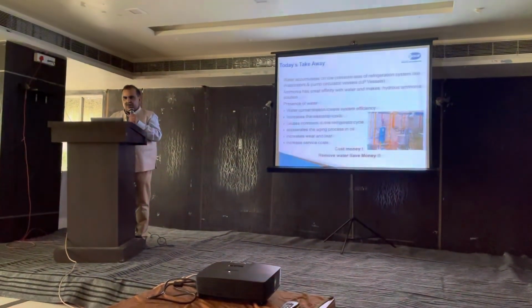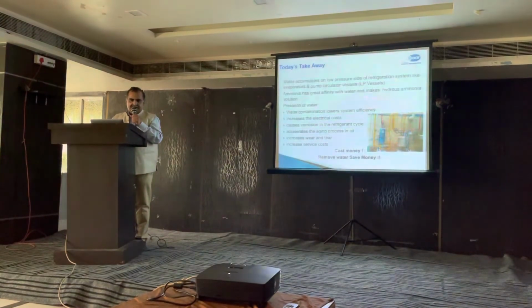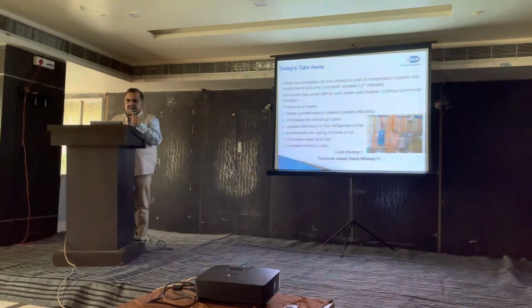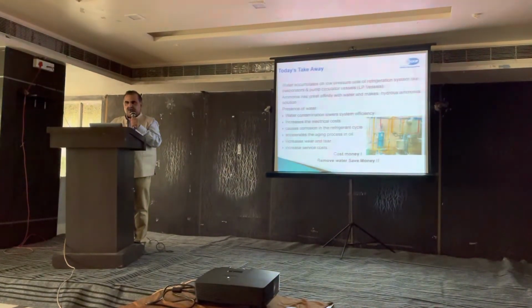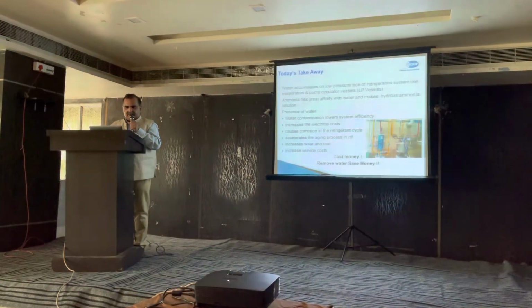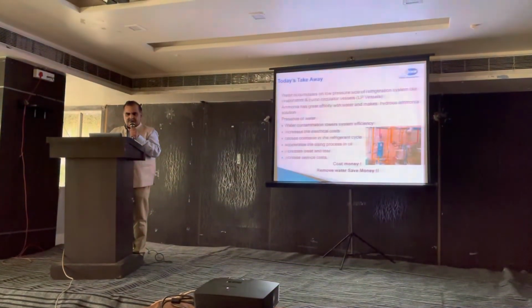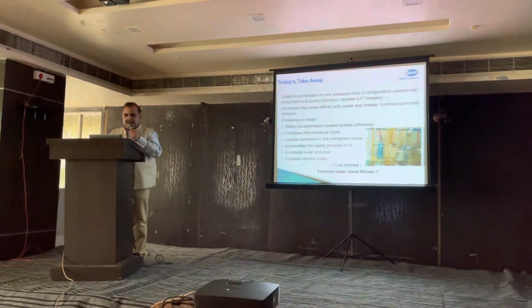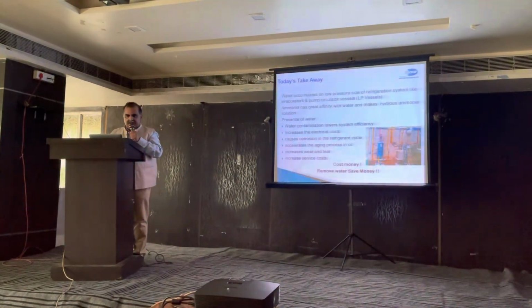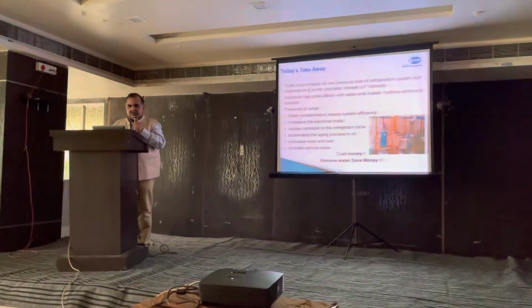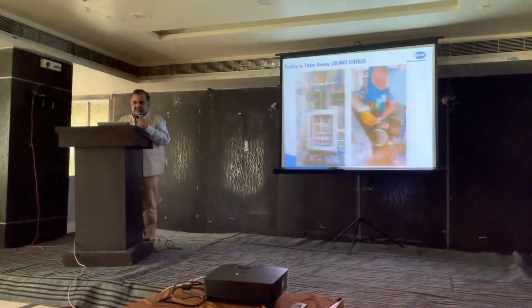Same thing is that water accumulates on the low pressure side, and when there is water present, the system efficiency goes down, the suction pressure has to operate lower, the electrical cost of the compressor goes up for the refrigeration capacity required. A lot of corrosion can happen. The oil will be damaged frequently, and it will damage other parts of the refrigeration system also. So it will of course increase the energy cost.